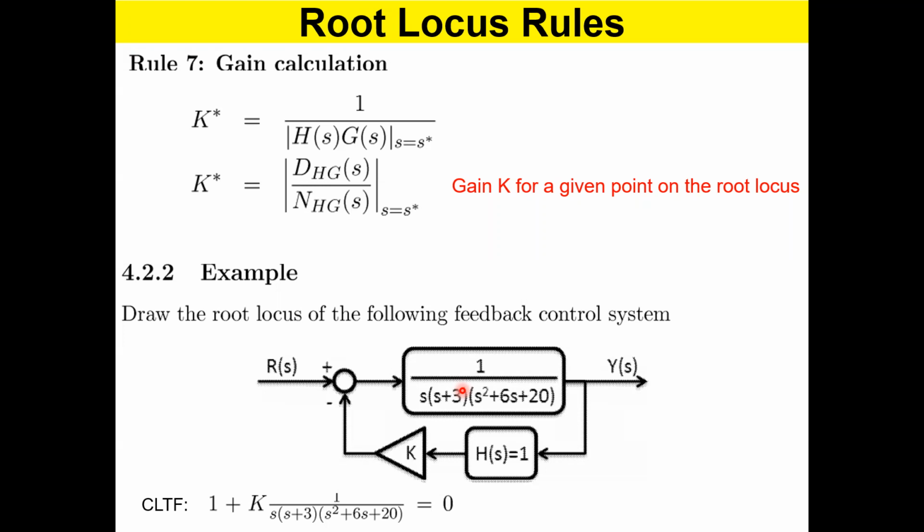Now, if you want to use this device and make it a feedback control loop, what you do is you take the output here, Y(s), and you connect it back to the input, not directly as input, but you compare it with a reference. Now, when you think about controls, you think about a reference. So reference is the desired response, actually.